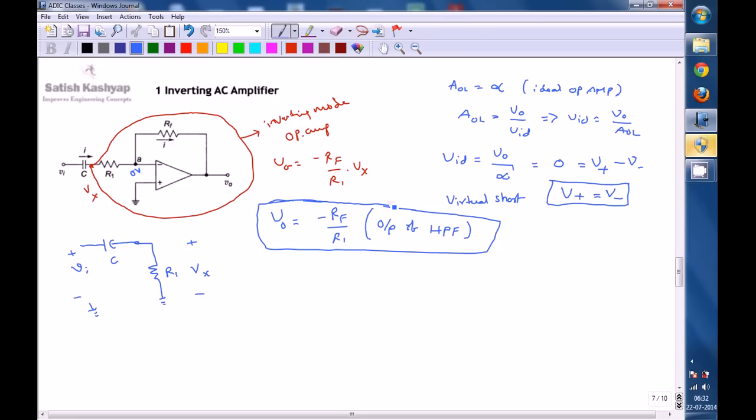If you use simply a high pass filter with RC components, the gain provided is at most 1, but you can provide more gain for the input signal by passing it through an op amp. Then it is called an inverting AC amplifier. We will see how to define the cutoff frequencies for this one.